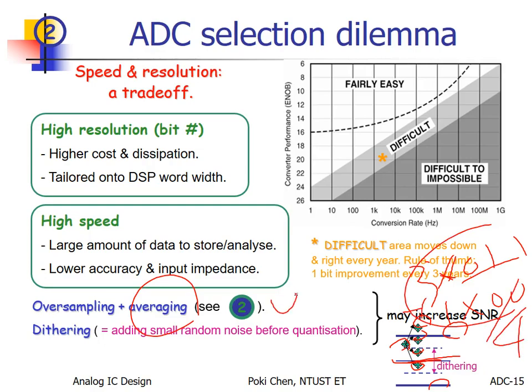You will get something like 0.1 or something, after the decimal point, then 1/2, 1/4, because this is in binary system. So oversampling plus averaging can help you enhance your accuracy.